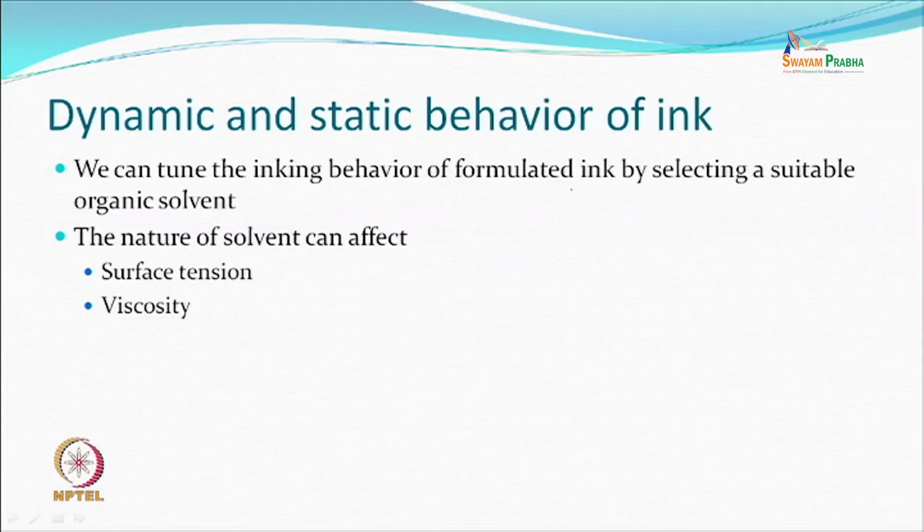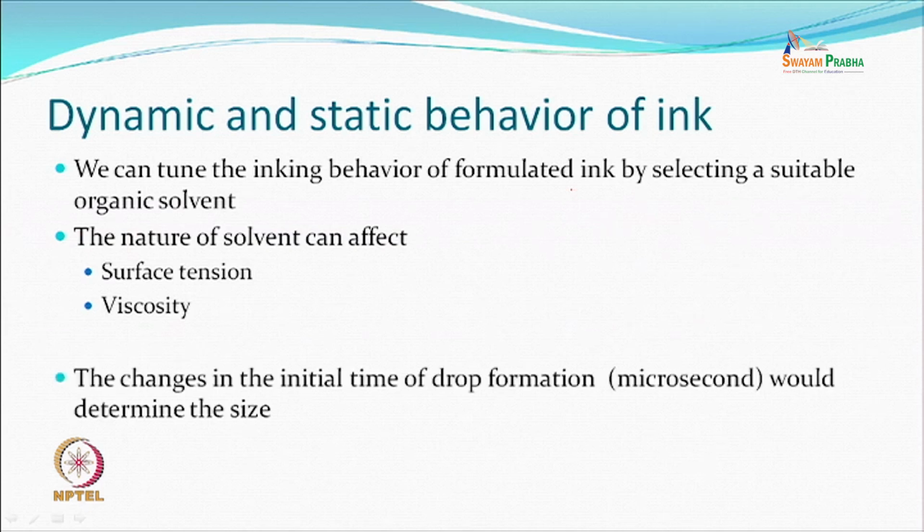When you add organic solvents, or anything, the evaporation rate can be changed. The nature of the solvent can affect the surface tension and viscosity. In the initial stages of drop formation, if these changes take place, they also determine the size, and how fast it has come. It is not necessarily that a certain amount of liquid displaced will become one drop. It may divide into many drops depending upon these properties.